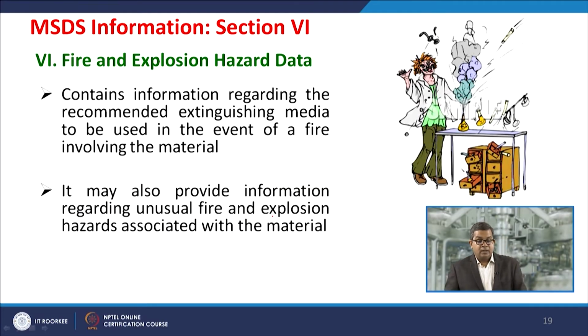The next section deals with the fire and explosion hazard data, because this creates another problem. Suppose like hexane, like LPG, etc. Everything which is flammable in nature may create a future problem. So you must know how hazardous that particular substance is in terms of fire.